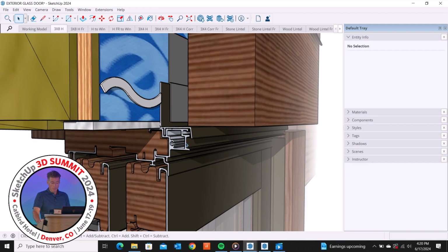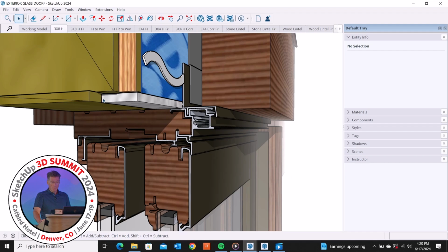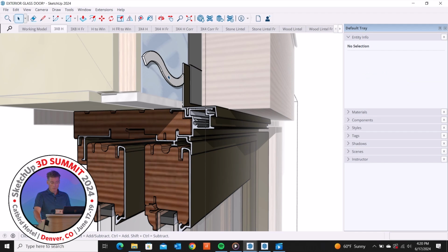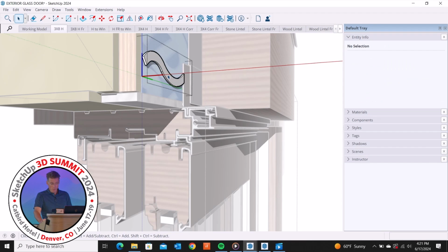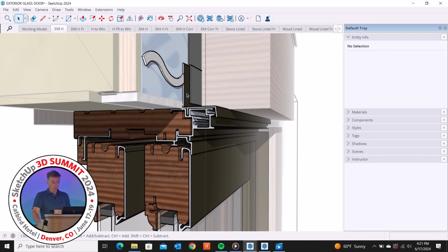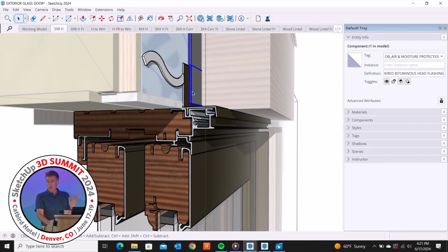So we have the nailing flange on this, in this case, a slider. It shows the shim piece, the foam insulation we use to fill the gap, the sealant that we use, which is Sikaflex 1A, and I think that's pretty common. I don't know about in the rest of the country, but there'll be that information. There it says number 2, but it'll be repeated right there. So you don't end up with that number 2 in your note. Because in some cases that detail might appear in a couple different configurations within a single detail. And I don't bother to go back and change that component name, then I'll just do it inside the group.